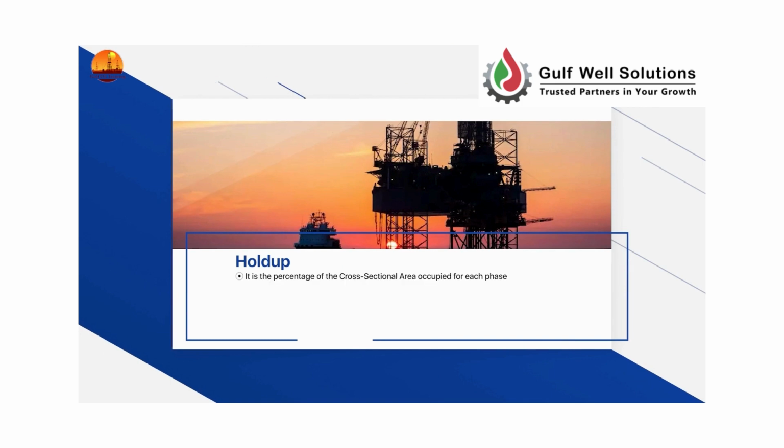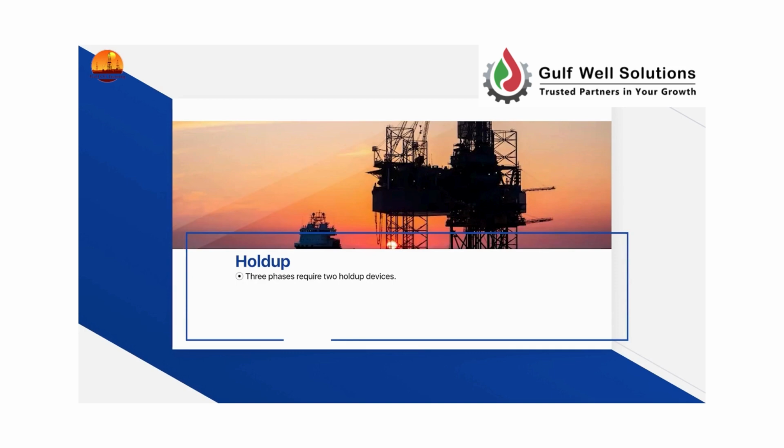Hold-up. It is the percentage of the cross-sectional area occupied by each phase present in the pipe. Single phase does not require a hold-up device. 2 phases require 1 hold-up device. 3 phases require 2 hold-up devices. The devices cannot measure the same fluid property. Phases are at downhole conditions.